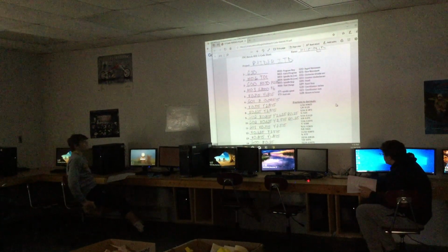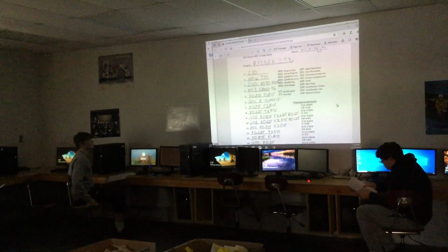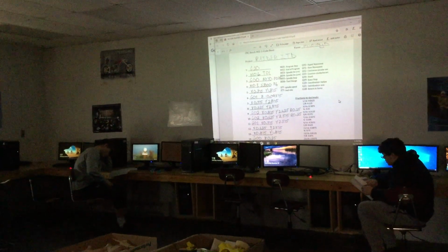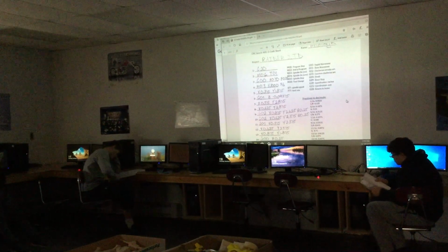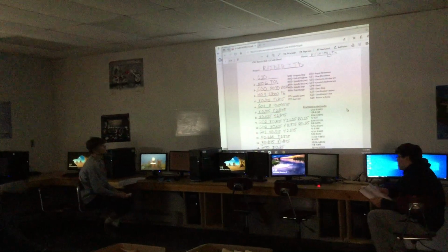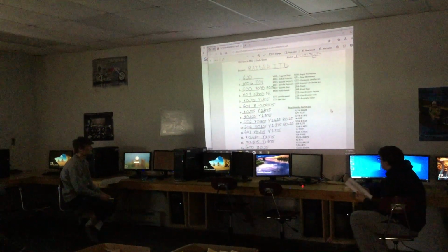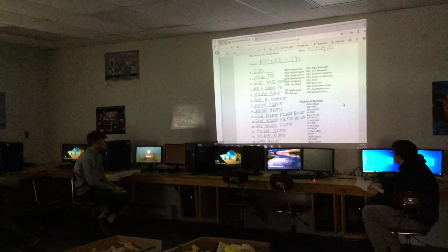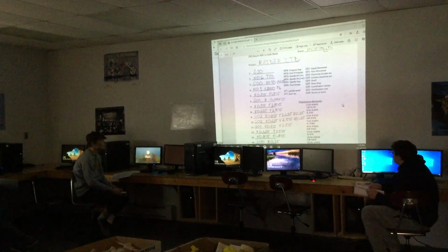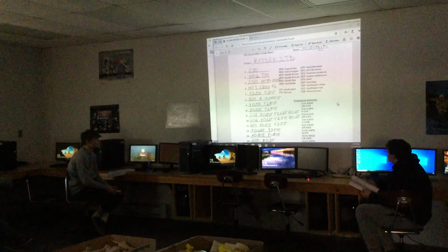What's the first code? G01. Remember, I was in G00, which was rapid movement. Now I'm in G01, so I'm telling the machine we're going to slow down, and then we're going to go down with the Z. Now this decimal I did not put in there. I just didn't have that set over because I didn't like the depth. I thought an 1/8 was too much when I was cutting it, and I thought a 16th was not enough. So I put in 0.09375, which is actually 3/32. How did I get that decimal?